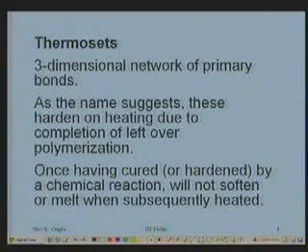Once it is made as a single molecule, you give it a shape, or sometimes the polymerization is done through a chemical reaction. Once it is given a shape, it keeps that shape. Before it can melt, on heating it degrades, combining with atmospheric oxygen. It is not possible for it to melt so easily because they are all primary bonds, sp3 bonds, which do not break so easily. So it does not soften on heating; rather, even before it can melt, it degrades.